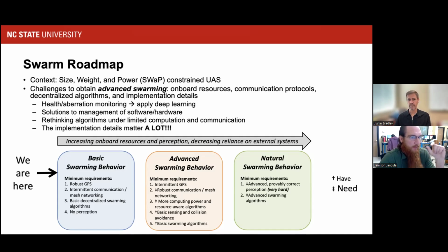Okay, thank you. I was also wondering, on your swarm, the only way they're communicating positions is through the ad hoc network? Yep. They all communicate with each other. There's a different radio system that's sending just telemetry data to a ground station so we can track them, but all of the intelligence is emerging from them communicating amongst themselves. So the ground station is not sending anything, it's totally just monitoring? Yep. Fully decentralized. All the behavior is emerging from the decentralization and the onboard intelligence.